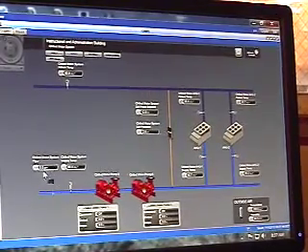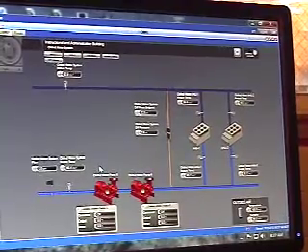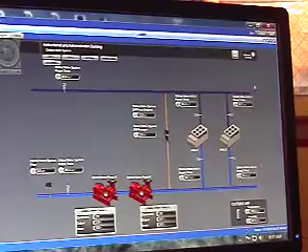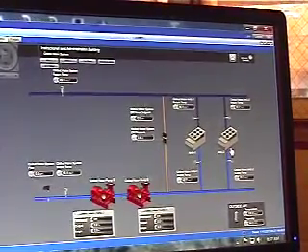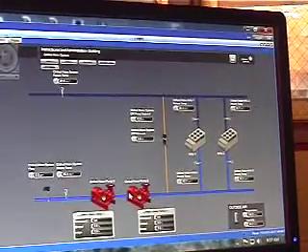We do have temperature sensors and flow sensors that'll provide some BTU measurements for you, some calculations, but they're not used for controlling purposes. We're just dumping water out to the space. You'll also have coil temperatures across your coils, so you can get an idea of what your delta T is across those coils.